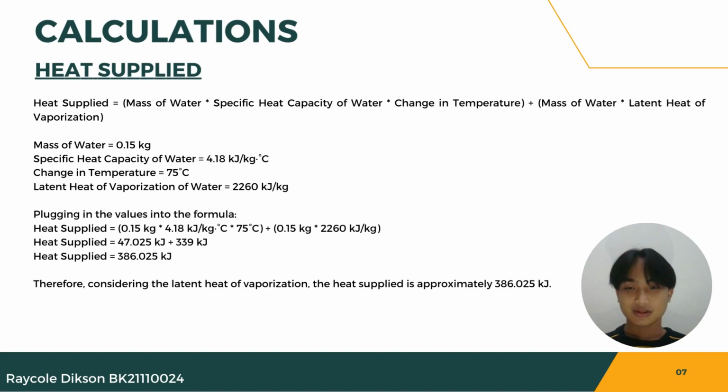I will now proceed to the calculation part of the presentation. The first calculation is heat supply. Heat supply is equal to, in bracket, mass of water times specific heat capacity of water times change in temperature, plus mass of water times latent heat of vaporization.